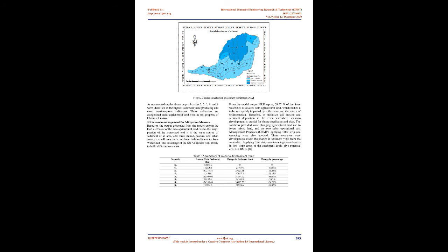After calibration and validation, the model was simulated for a period of 30 years, 1989 to 2018. According to the result from the model, hotspot areas have been identified in the watershed. The corresponding spatial visualization of subbasin-wide sediment yield in tons/ha is shown in Figure 3.9 below. The SWAT model simulated annual average sediment yield was 8.80 t/ha/year.